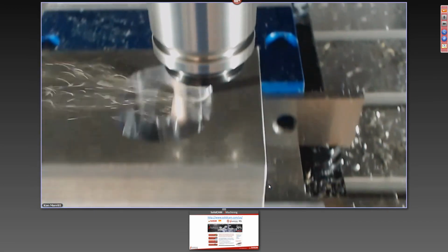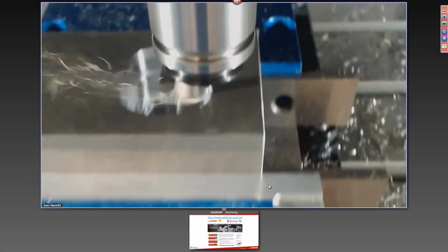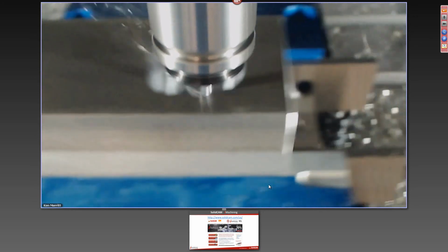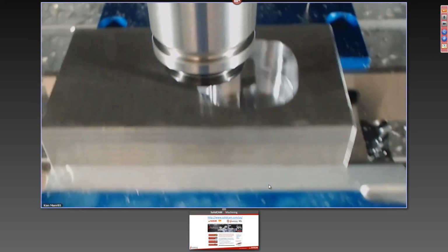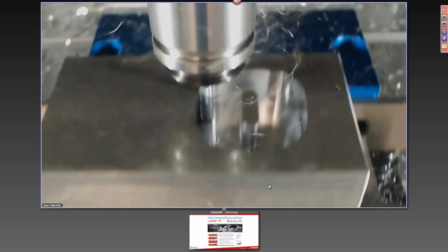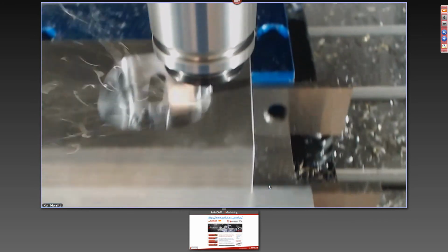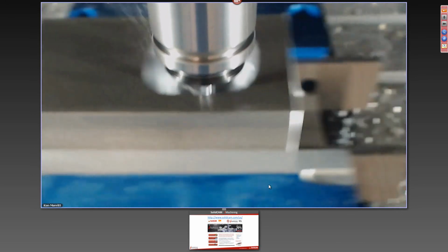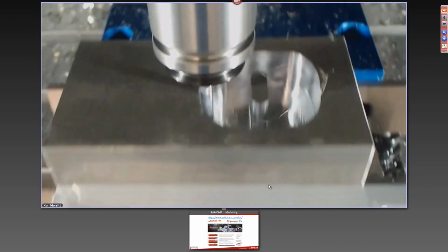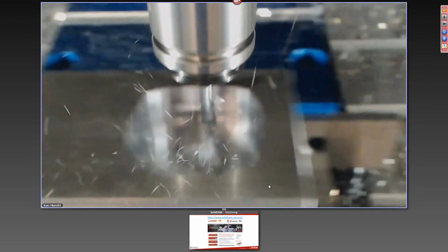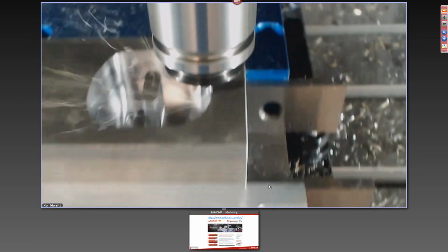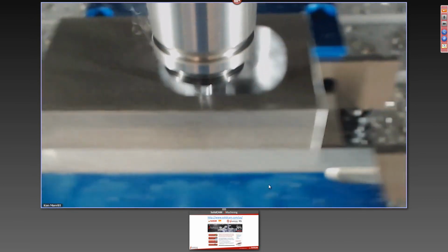And in this spiral morph, I'm looking at about a 15 to 18% spindle load. So it's really not taxing the machine very hard at all, and yet look how quickly we're removing this material. And again, with just air blast, no coolant. All I have to do is make sure I get those chips out of the way. We don't want to run over chips, so I need enough air blast in there to blow the chips out of the way.